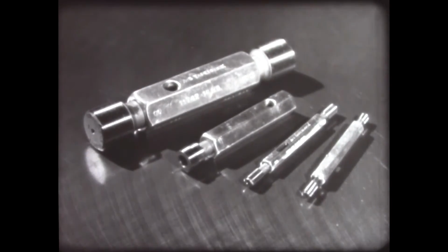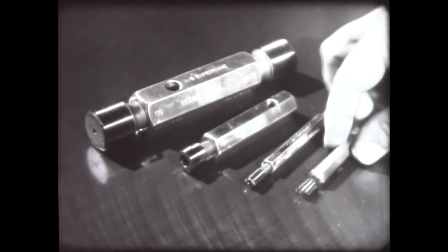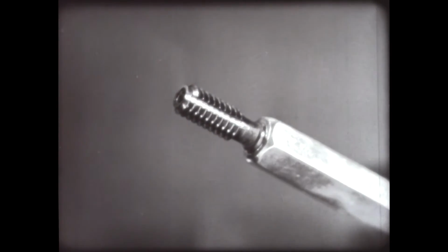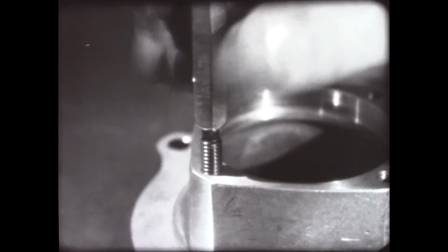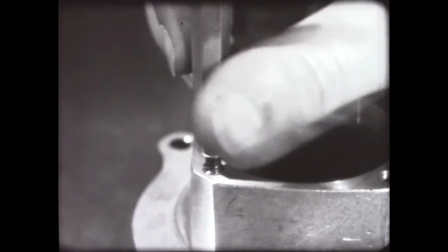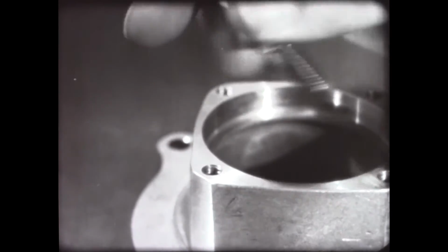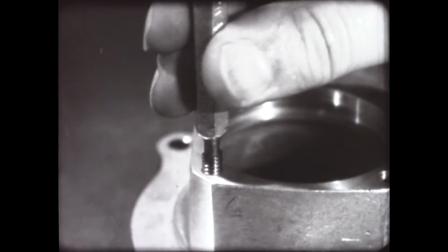The higher step should be flush with or be above it. Screw plug gauges used for checking internal screw threads are made in a large variety of sizes and shapes. Screw plug gauges usually have a chip groove cut for the full length of the thread on the go end of the gauge for the purpose of clearing chips out of the thread to be gauged. The gauge should enter the hole freely and should be run down to the bottom. The not go end should not enter the hole more than 1 1/2 turns.